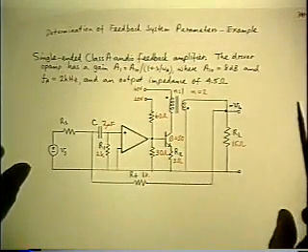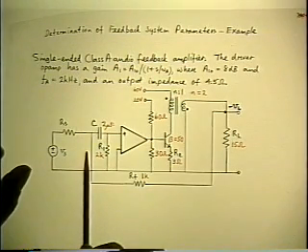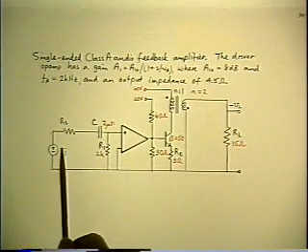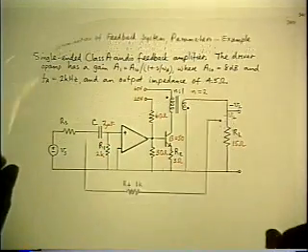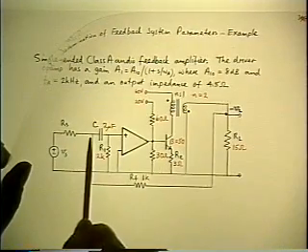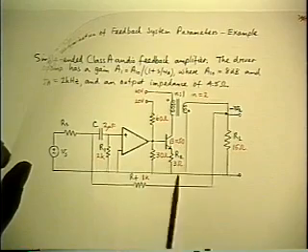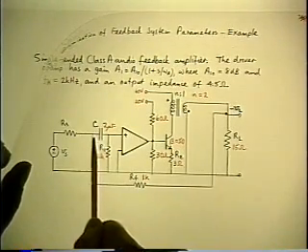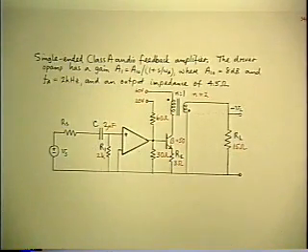And the same problem applies at the front end. In fact, this case is even worse, because when you disconnect the feedback path, you've changed the loading of the input as well, and you've changed the gain from VS to the driver, which is part of the forward path. And if you try to fix that one up, you draw RF from this point, but you have the same problem. What do you do with the other end of it? Because it doesn't go to ground, really. So that's going to affect the current division in the forward path, and therefore its gain, and you don't know what to do about that either.